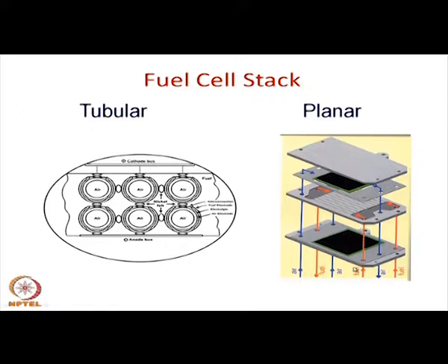So, that is one thing. The other thing is, this is your interconnect, that means I have shown you earlier that there are grooves on both the sides. This is one kind of groove, and below also there will be another groove. That groove may be crosswise or in parallel grooves, but on one side the fuel passes through the grooves, on the other side it is the air which passes through the grooves.